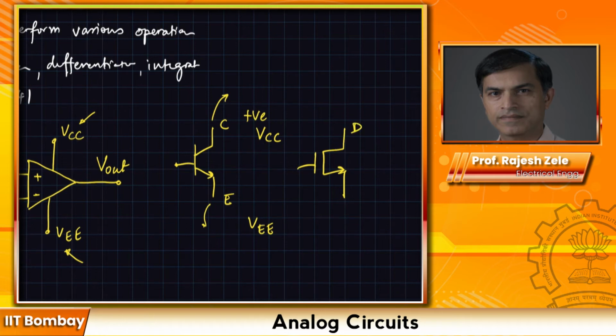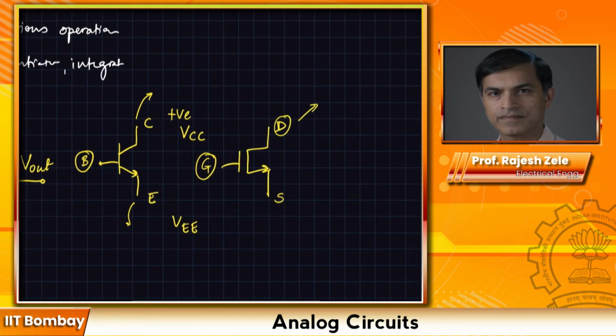Similarly, if you are using a MOSFET transistor, let's say this is an NMOS transistor, then you have a drain region and a source terminal. So drain and source, and this is your gate. On this side is the base of the transistor. Generally the drain goes to the most positive supply. For CMOS circuits, the supply is defined as VDD, and the most negative supply is referred to as VSS.